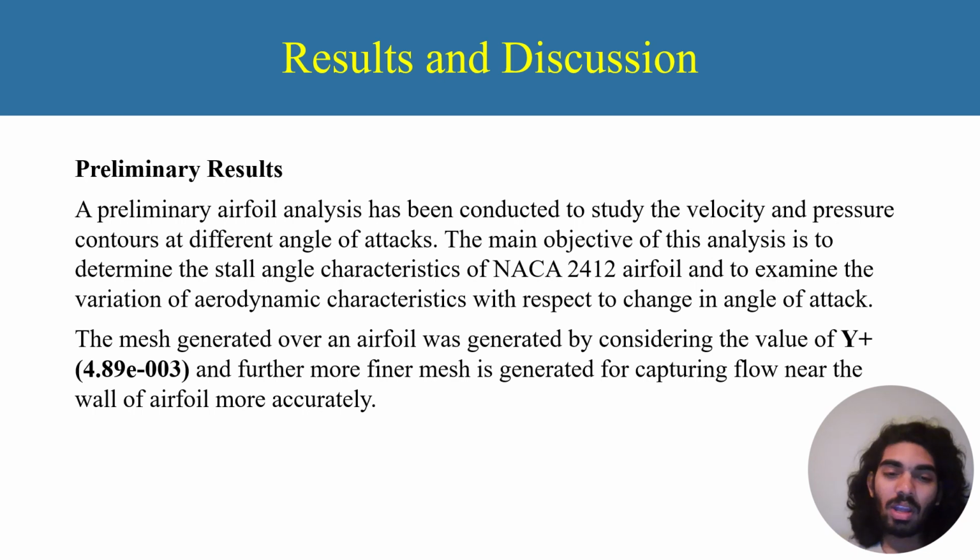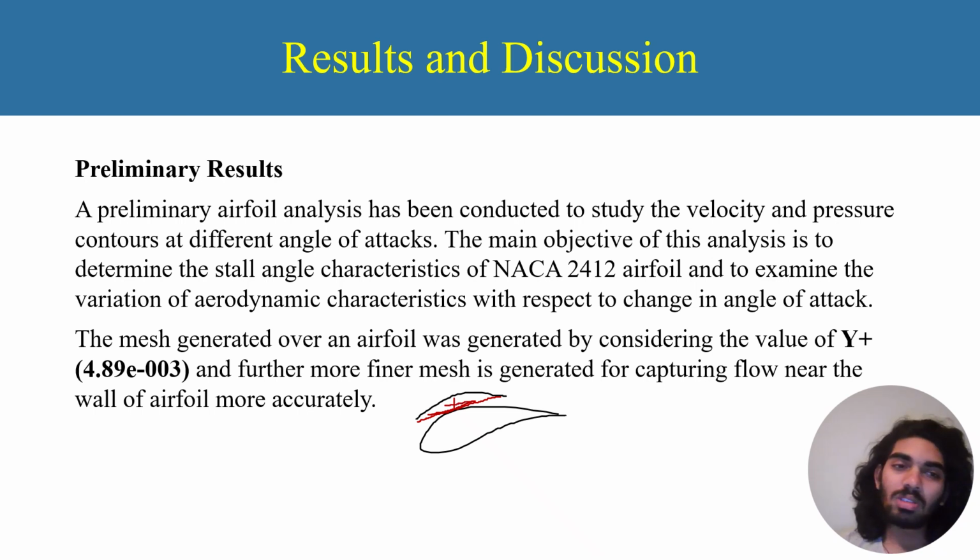So this is going to be the airfoil. If we consider this is the first layer, then this height, the height between the edge of the airfoil and the first boundary layer, is going to be the y plus value. So we give the y plus value here. If we give the y plus value like this, we form the mesh in this region too, so that we can study more about it.